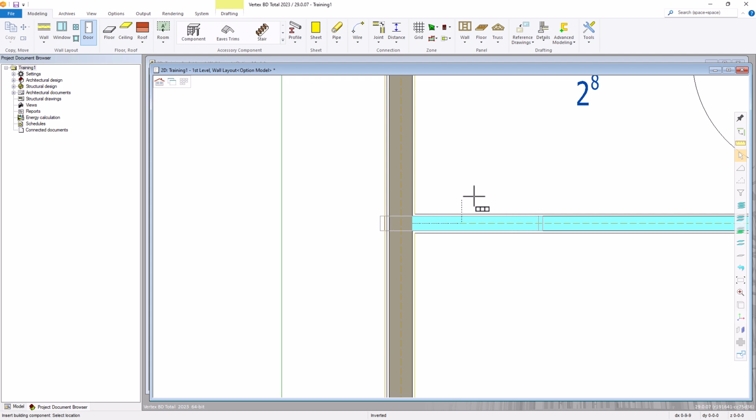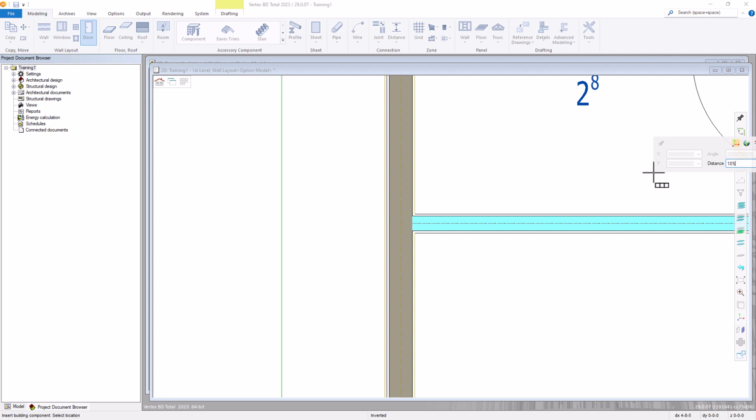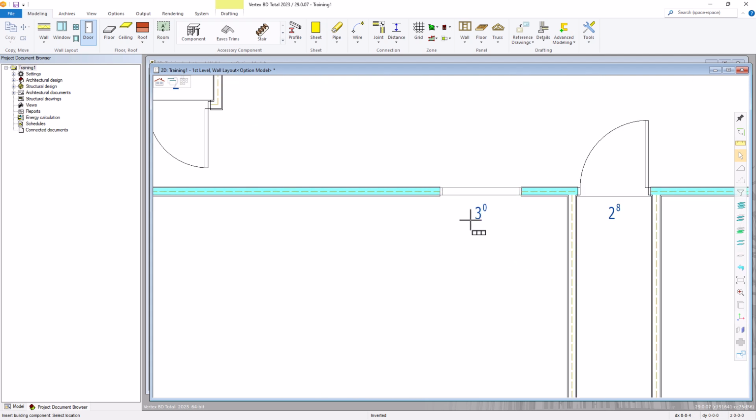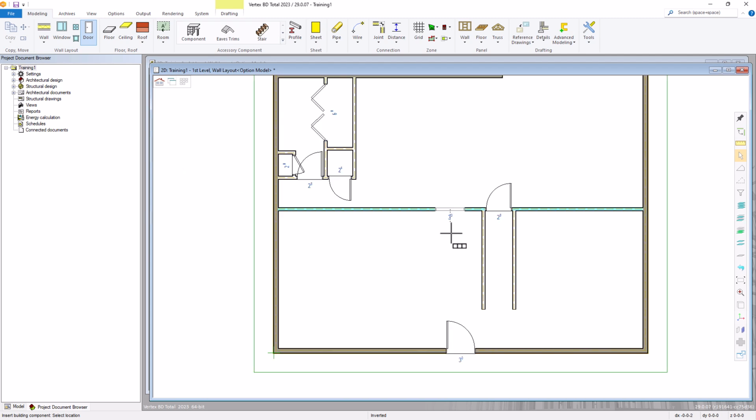And from that point, we're going to pull the door over to the right and type in a distance of 18 feet 5. Oops, 18 feet 5. Do not need the inch mark after the 5, but you do need the foot mark after the 8 there. And select return. And if we zoom out, you'll see the cased opening over next to the other door.